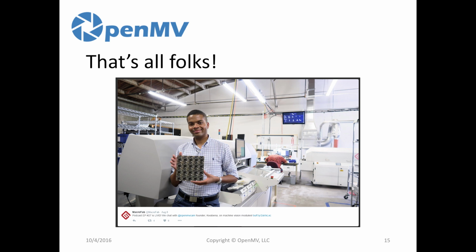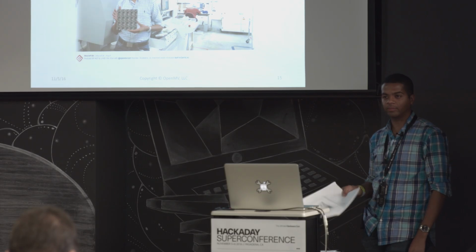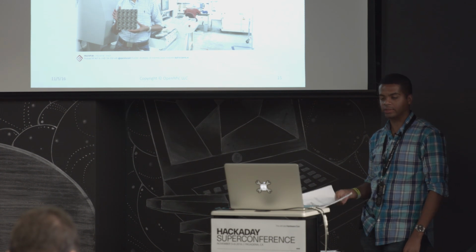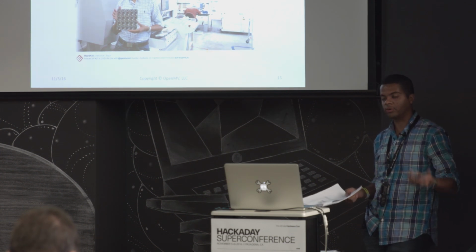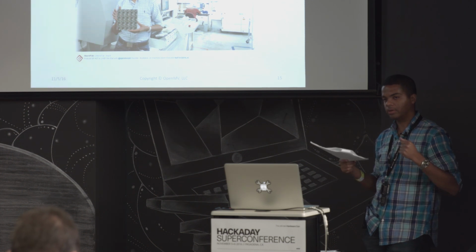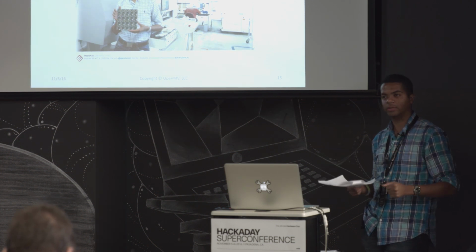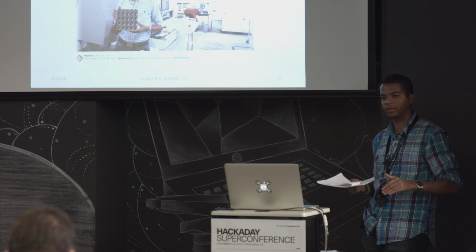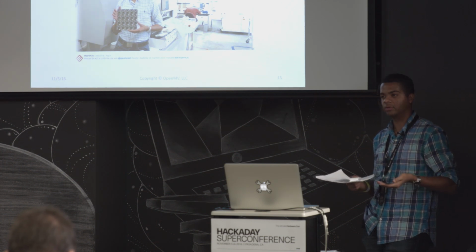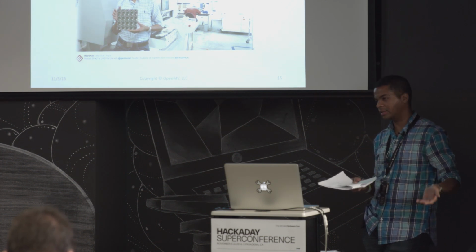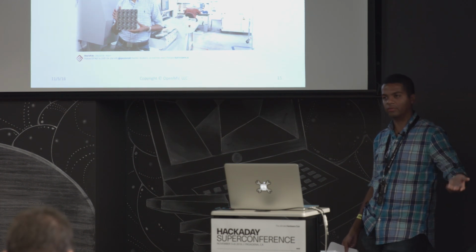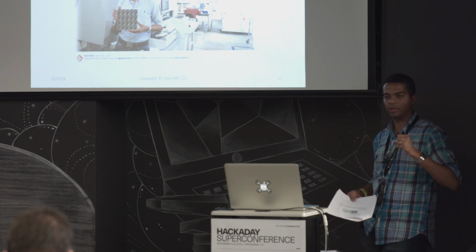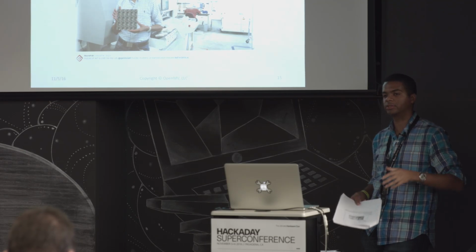Thanks for listening. And also, before I go, I just wanted to give a shout out to Macrofab. They're our contract manufacturer, and they stuck with us the whole way. They were actually in charge of diagnosing this problem. They were basically trying out all kinds of medieval methods to make sure those solder balls worked. They actually tried grinding the bottom chips, using extra heat, dipping them in acid, reballing them, all kinds of crazy things to make these cameras work before we finally gave up with the OV2640 camera chip and switched.